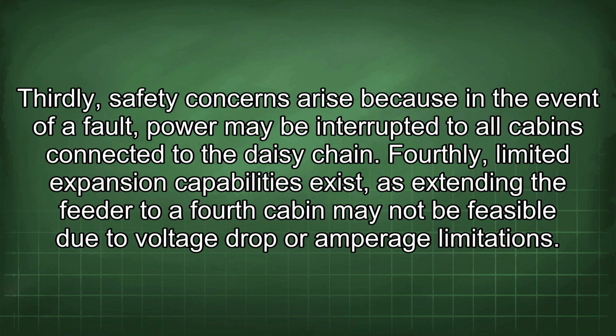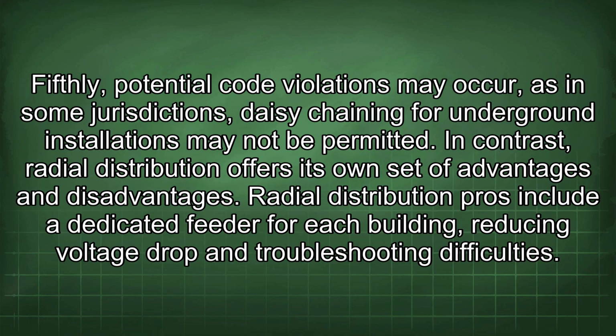to the daisy chain. Fourthly, limited expansion capabilities exist, as extending the feeder to a fourth cabin may not be feasible due to voltage drop or amperage limitations. Fifthly, potential code violations may occur, as in some jurisdictions, daisy chaining for underground installations may not be permitted.